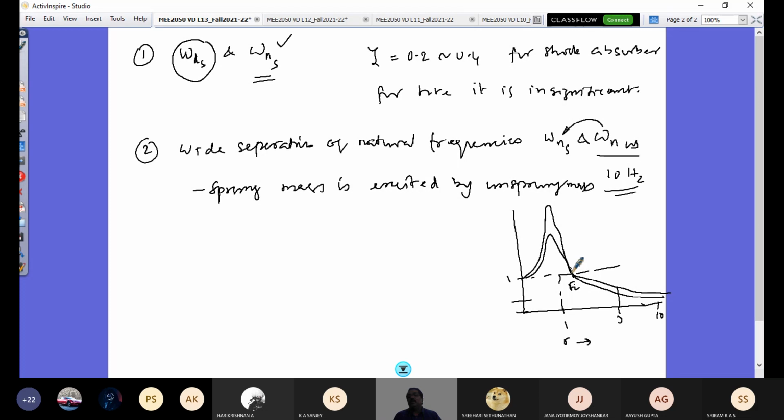It comes when the excitation frequencies from the road are closer to this zone, around 1 hertz, 2-3 hertz. It is inevitable that energy enters. As you see, it may not be amplified, maybe it is attenuated, but some energy closer to this zone can enter. That cannot be avoided, and that is where you have other mounts and the seats, where occupants are seated and their amplitude of vibration is kept under control to meet the requirements of the SAE or ISO 2631 standard. We are going to see them all in detail in our upcoming classes.